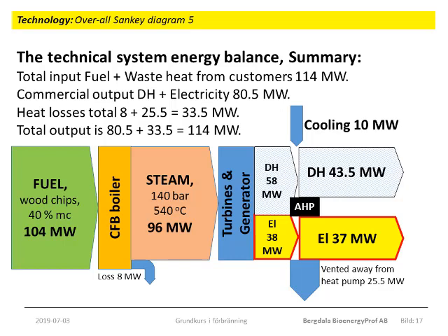The waste heat is brought into the absorption heat pump and is vented away together with the heat energy needed to take out the waste heat from the water where it was stored when it came from the customer. From the heat pump is also vented away the electricity needed to circulate the absorption liquid inside the heat pump. So in the overall heat balance, the cooling shows up as an input and as a loss.